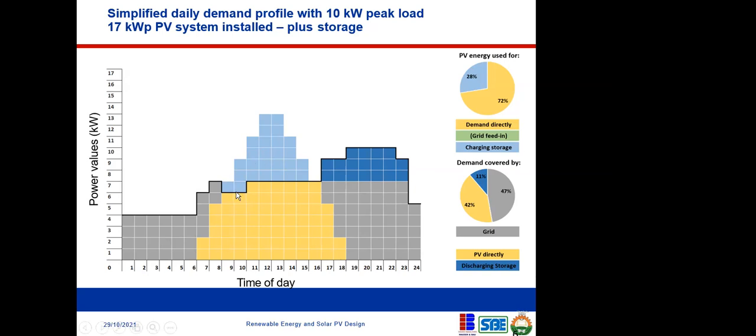During the day when the sun is fully out and you're not consuming all the energy that is coming from the sun, then the part of the energy that you're not consuming can be stored in the battery system, so that at night when the sun is no longer out there, it can blend with the grid. Okay, the energy from the battery can blend with what's coming from the grid, and then help you to reduce your consumption from the grid, and then actually reduce your energy cost as well.